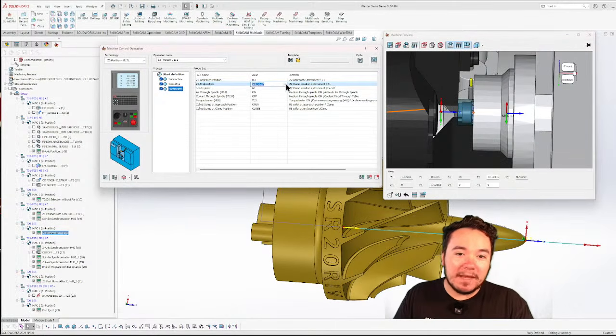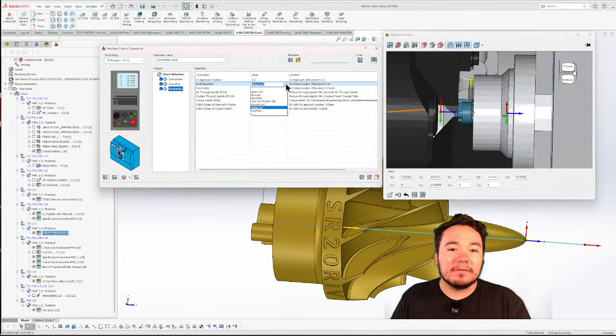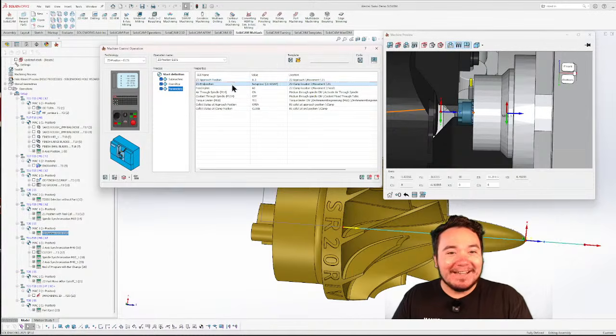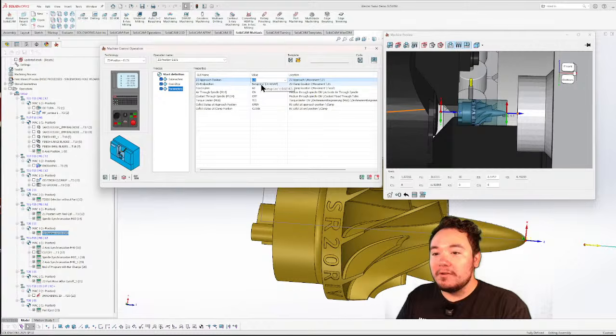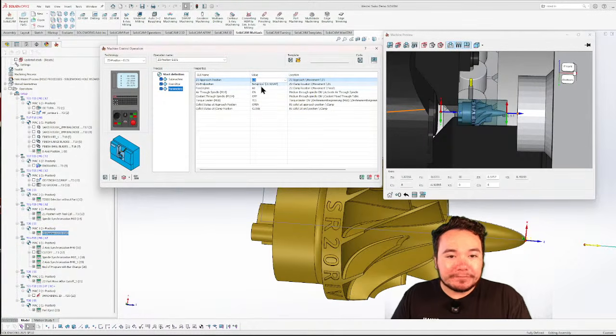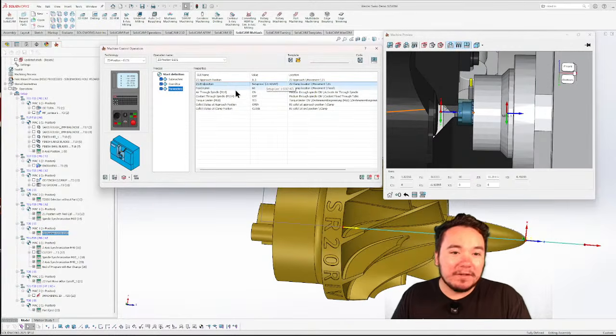You can actually grab that by just hitting this drop down right here. You can put in all kinds of stuff. I like doing it setup location just so it makes it easier for me, and I don't have to do it again here. If I do it once in the setup, I don't have to do it again. And my approach position is going to be 300 thou from Mac 1, from the original work offset. So it stops there, and then it goes to the end position, and it feeds on at 60 inches a minute. You can change to whatever you want.